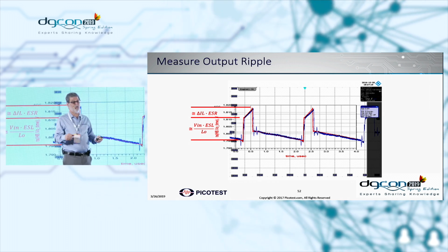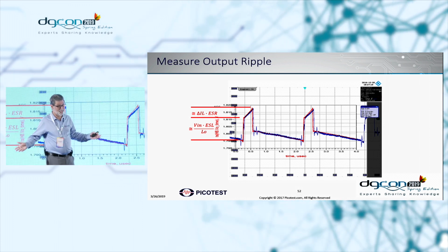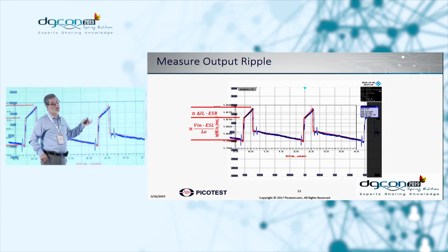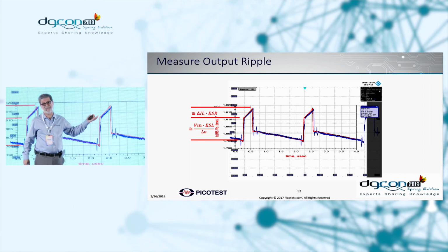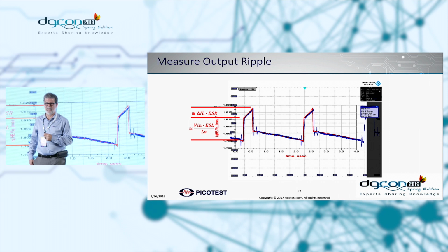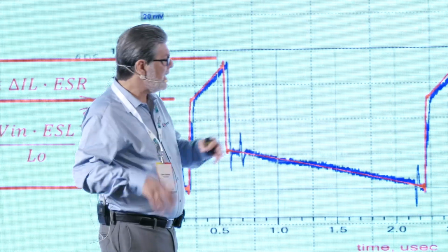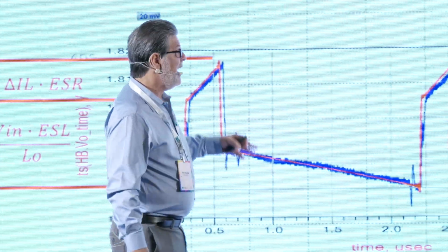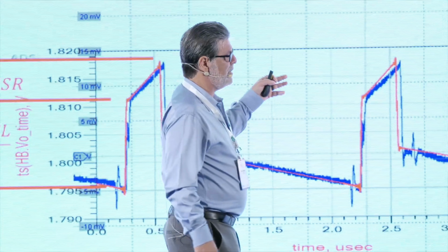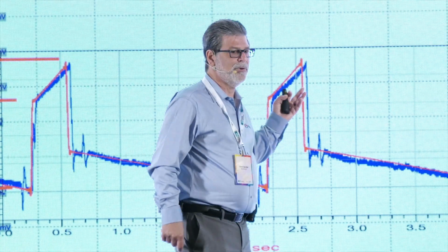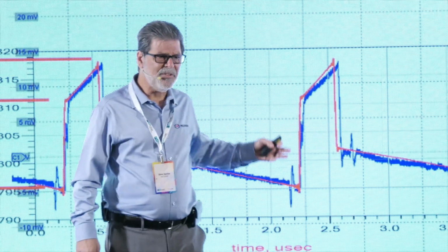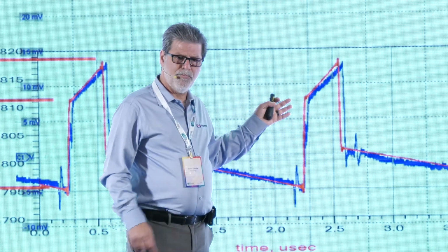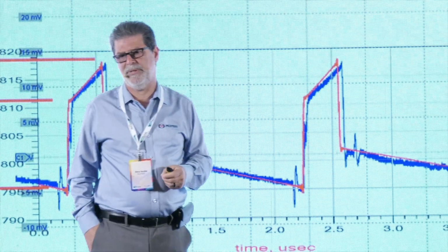And so in order to improve their impedance, I had to give up something. What can I give up? I only have so many knobs. I can give up ripple, I can give up efficiency. In Xilinx's case, I actually had to give up both. But there's only so many things we can give up. I have an article in Signal Integrity Journal now called Power Integrity versus Power Electronics, the Ultimate Lose-Lose. And this is also a reason that we really want to have these high fidelity models.